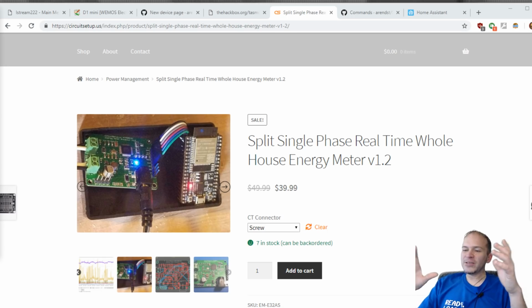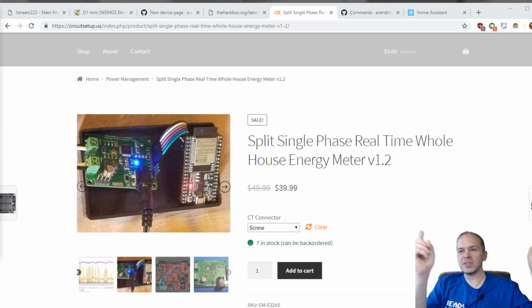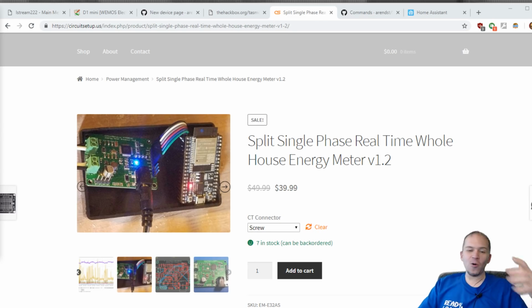I've done this in one house, it's not smart related. We were putting new garage lights in, getting rid of the old little single fluorescent ballasts and putting separate lights around the garage. And I just didn't feel right about some of the wiring in there. So when I was wiring up to the switch, I actually went in and cut the whole house off. I just said, hey, to hell with it. We turned the whole main breaker off, turned everything off, so I wouldn't have to worry about it. So that's it: if you don't feel right about it, just better be safe than sorry.